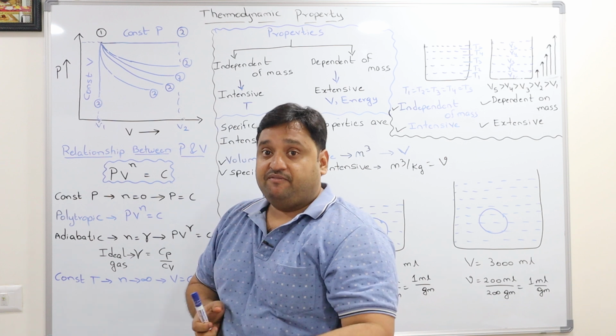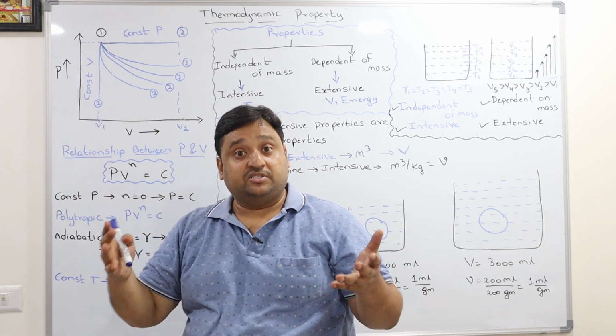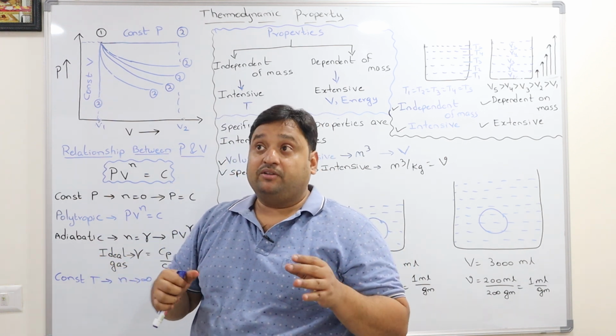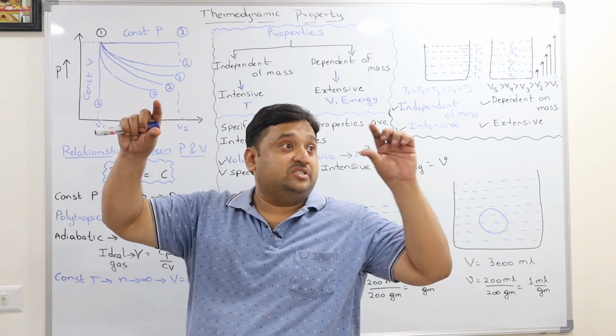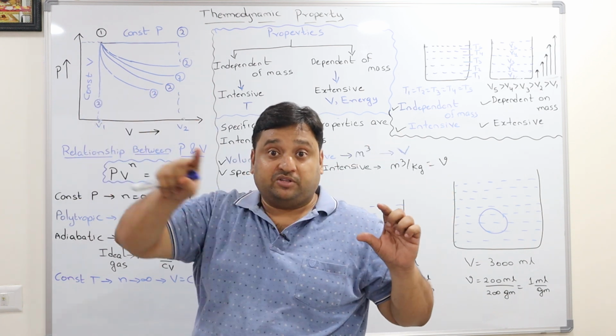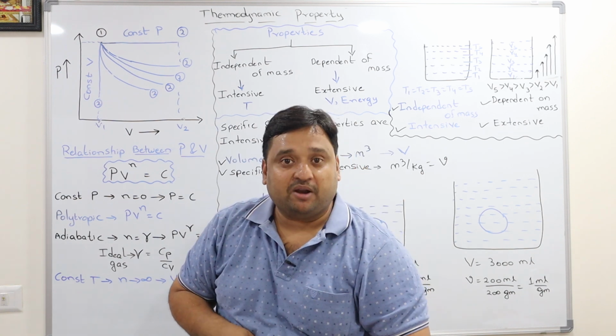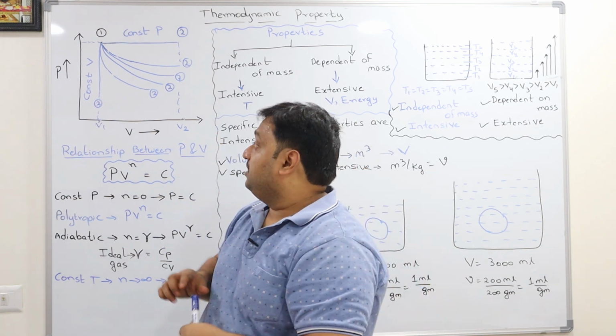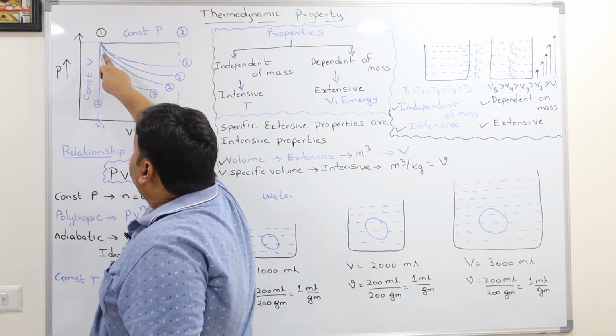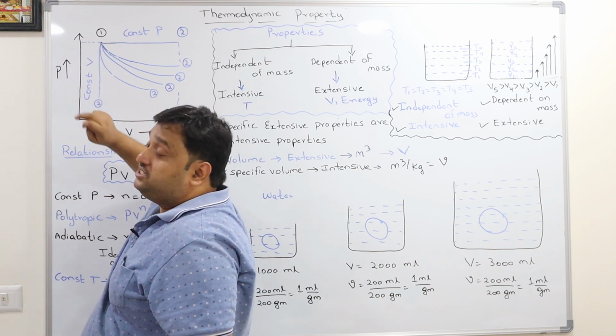So there are specific formulas. If a process happened which brought the system from state 1 to state 2, and you know what process it has undergone, you can find out the heat and work requirements as per the process. And you can see this line is a constant volume process.